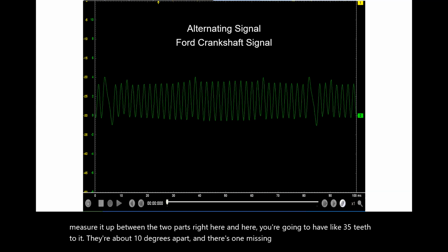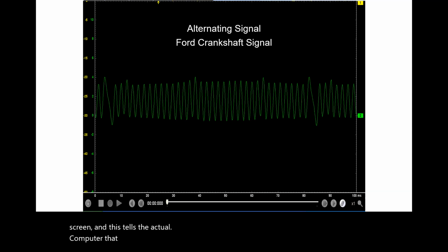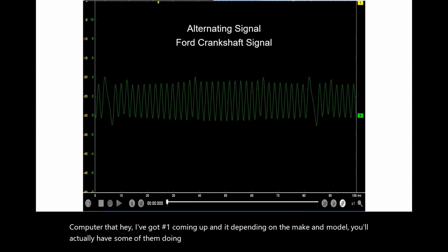Instead of being 36, there's one missing, and that one tooth that is missing creates that pattern that you see on the screen. And this tells the computer that, hey, I've got number 1 coming up, and depending on the make and model, you'll actually have some of them doing that at certain degrees too. So this is a good example of using an alternating current for like a crankshaft sensor.